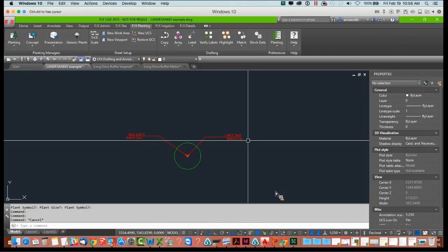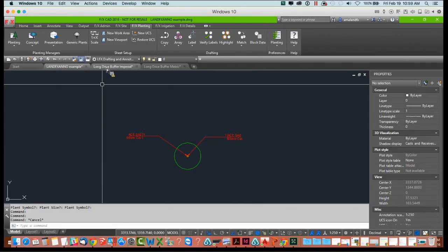I mean, I would just say in terms of line type scale, particularly with irrigation, Jimmy had a quick question on that, and I just directed him that is really more of an issue of sheet setup, the nature of how LT scale works. So for those of you, and that was our bad for not being very clear in this webinar. But the nature of how AutoCAD works, line type scale is actually more a factor of your sheet setup rather than what's covered in this webinar.